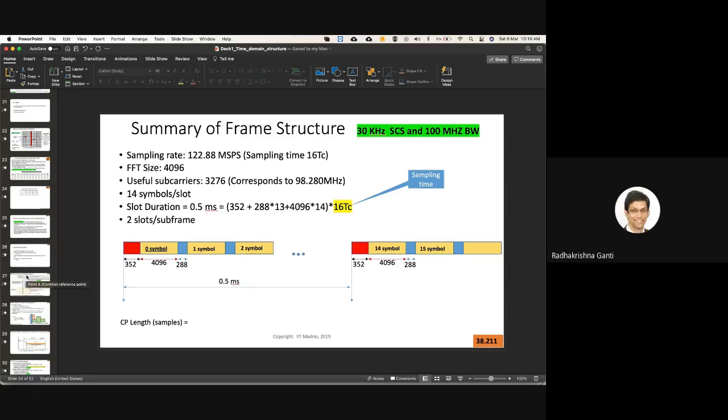Exactly. In millimeter wave, the beams are very narrow, just pencil beams. That's why generally people think of them as almost like an AWGN channel with a gain. Right, very flat channels. It depends on the exact frequency or the reflectors, but what you said is absolutely right, sir. That is the reason why they do not consider very large cells. Even if there's a large cell, there is not too much delay spread.